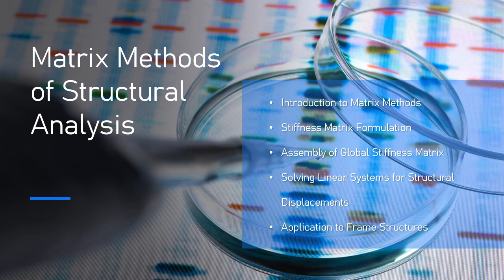Update the displacement vector iteratively by adjusting it in the direction of the residual vector. 4. Repeat the process until the residual vector is sufficiently small, i.e., convergence is achieved. The conjugate gradient method is highly efficient for large, sparse systems, and it can converge very quickly with a well-chosen initial guess.